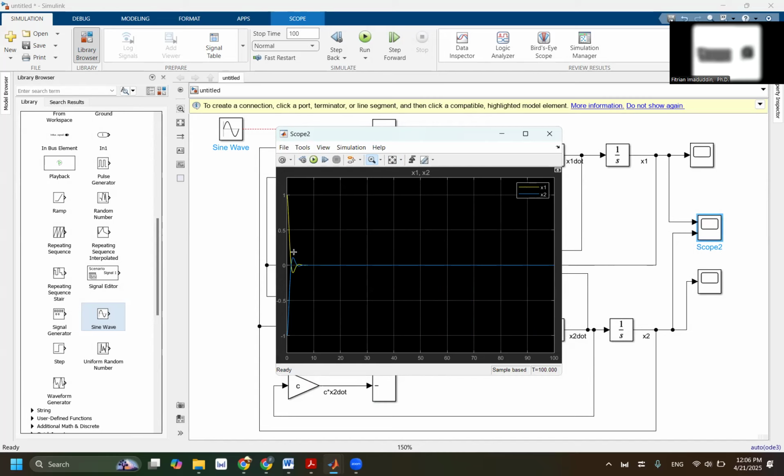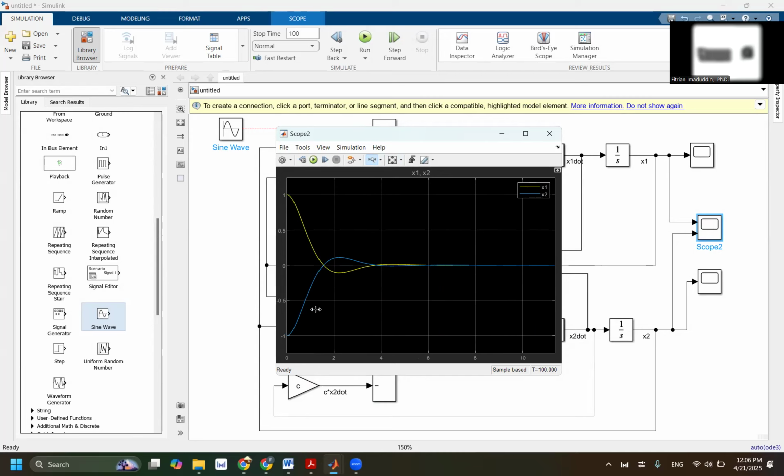This is supposed to be 100% second mode, where in the beginning you have something like this. You have opposite. Initially, x1 is moving at 1, x2 moving at -1. In the first wave, it will intersect, but then, because of the damping, it's gone. Now, this is what happened in the transient response.